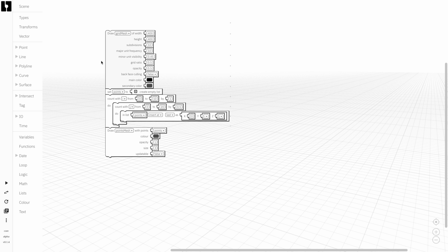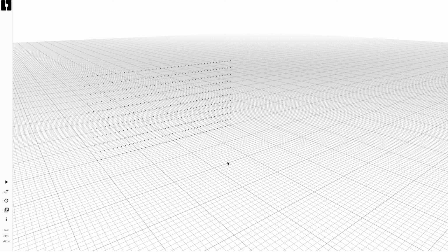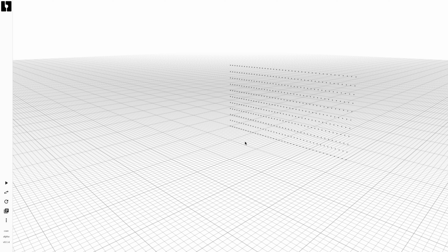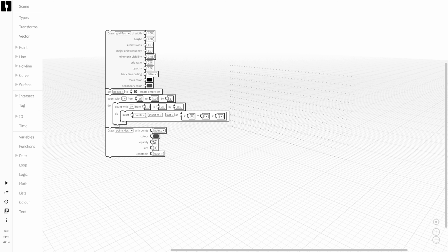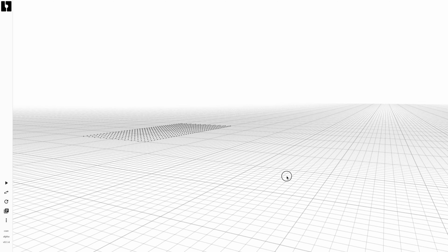And with this, you can see that now I've just created a grid that is vertical, and that has 10 points going upwards, and then 40 points going to that side, because we said that we want to go from 0 to 20 at 0.5. That creates us 40 points, and that's how it works. And with this, you can begin also seeing the pattern, so you could say, I want to create the grid that is planar, and this is then also the possibility to do that. So y is then static, and you can say I want the grid to go up, or I want the grid to go down to 0. That's all possible, and that's easy to do.